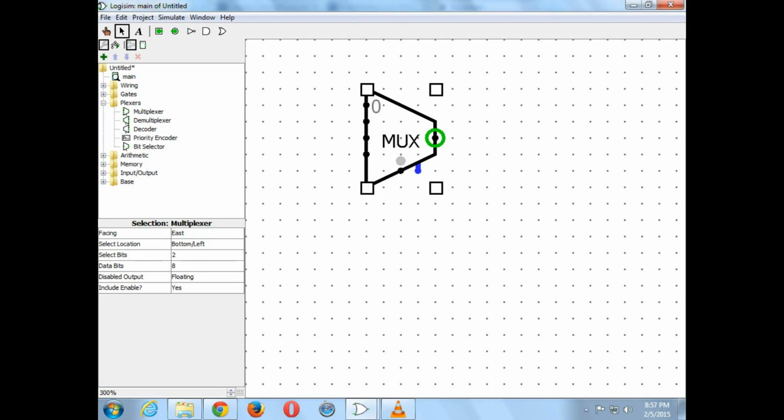Okay. So disable output is selectable, because you can basically say, if the output is disabled, what should it do? Floating is what we are choosing in the design because we basically say do not drive it. The other option is 0, which means you're driving it low. Now, if you're driving it low, that means the same physical wire, the same physical connection on the motherboard or inside the processor, can no longer be driven by someone to a high signal. And we don't want to do that. We want to leave the option for somebody else to specify the signal on that line.